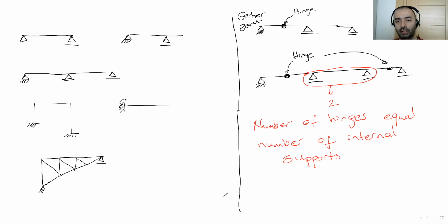If we are expecting different settlements, we use this type of beam in the structural system. When that settlement occurs, our beams rotate on these hinges. So it doesn't create extra internal force in my structural system. This is a kind of fuse for my structural system, actually.